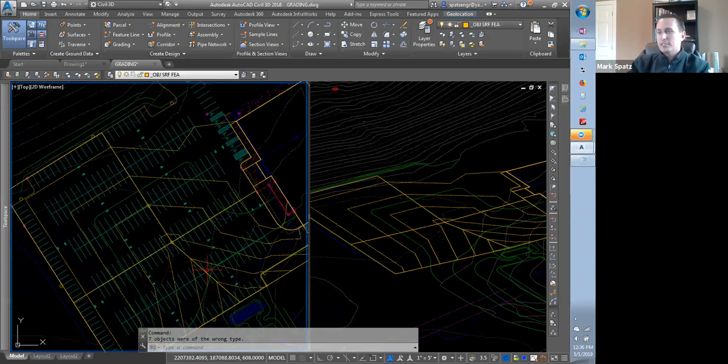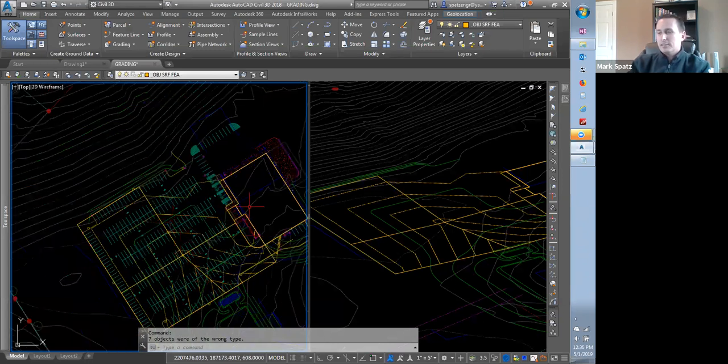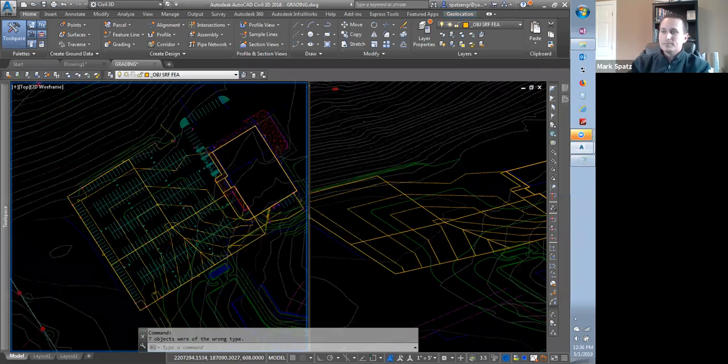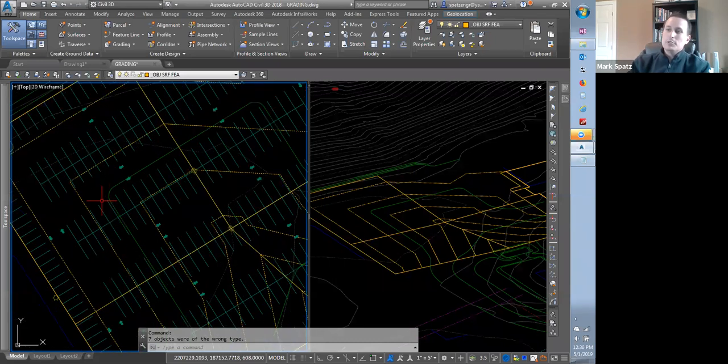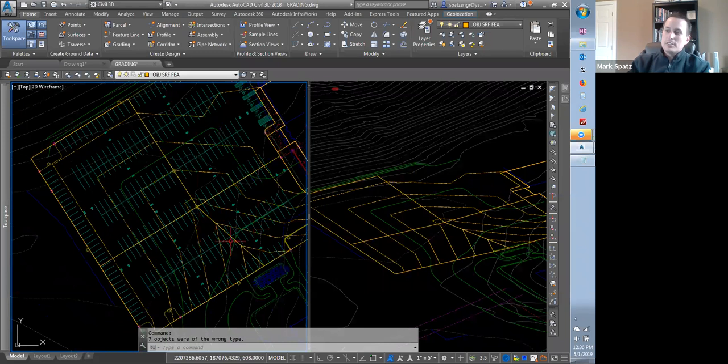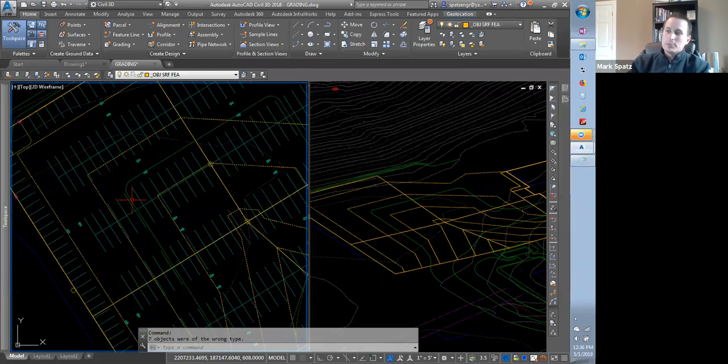You can start to see where there's work to do. It's not done, but we're starting to get this valley down through and across here. What the computer is not going to do, see how we don't have the same elevations as everything? We didn't draw this side over here. But you see how these contours are, so add those to your break lines.